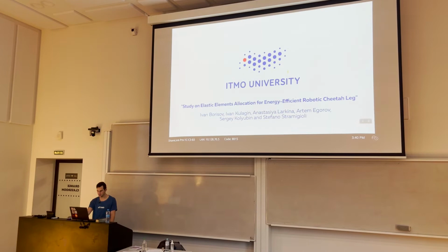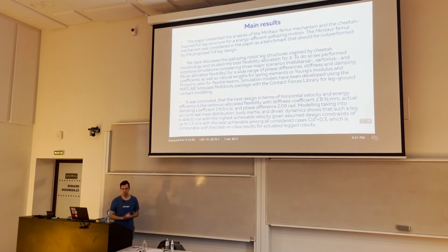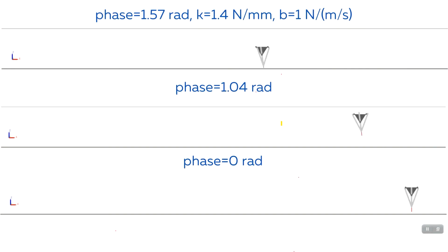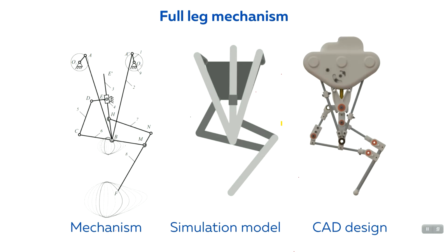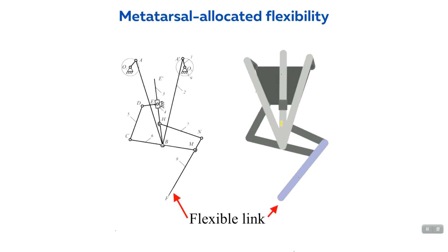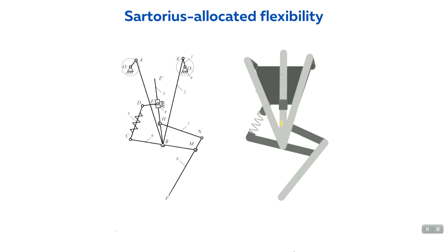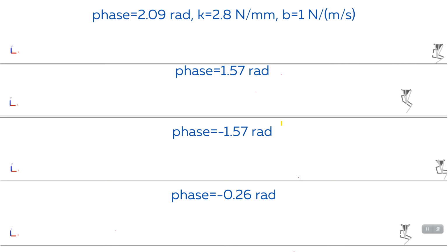Another example here is all about galloping robots, legged robots with passive elements. Those structures are able to gallop due to the resonance-based behavior of physical elastic elements. So there are springs, and our task was to synthesize a mechanism which is able to use real physical elastic elements, such that the design will be more energy efficient than galloping robots such as Spot, ETH, Unitree, and other kinds of legged robots that we can see right now.